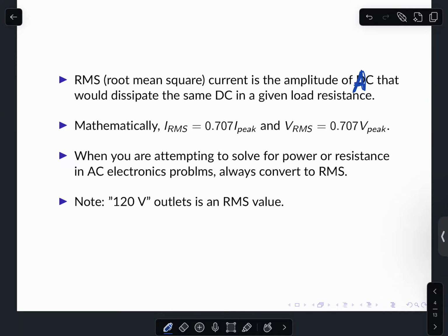So in math class, once upon a time, if you have graphed y equals sine x, you look at amplitude as the height of the wave, not with RMS, baby. To get RMS, you have the mathematical equation. RMS value is 71% of, 0.707 times the peak value. Voltage RMS, anything RMS is 0.707 times the peak value.